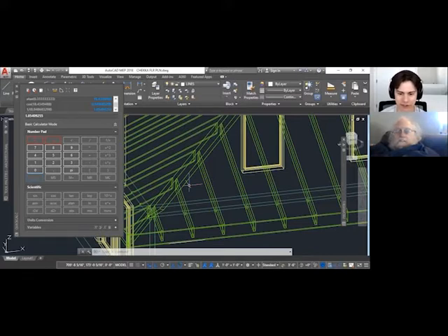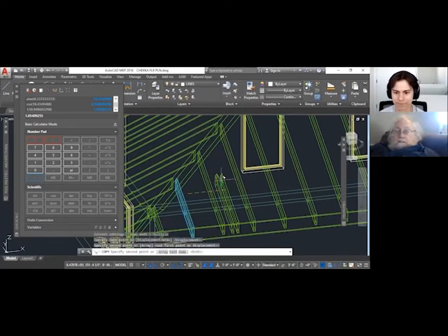I have a couple questions. Long point versus short point. The long point is on the top connection? Nope. The long point is, you've got a bevel. You have to set your saw at a 45-degree angle to make that cut. See how that jack rafter, let's copy this jack rafter over here so you can see it without it being on the hip. Good idea. Now let's zoom into it.